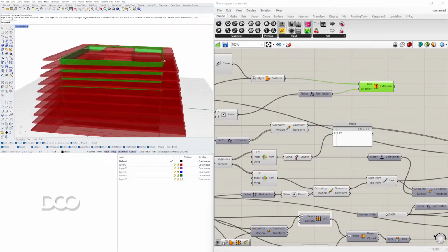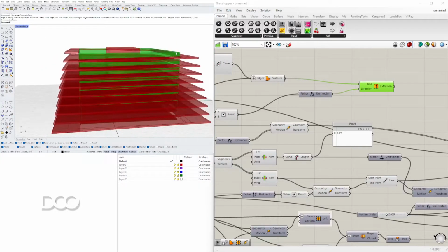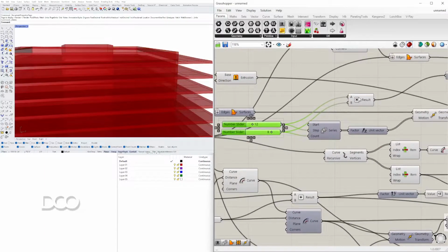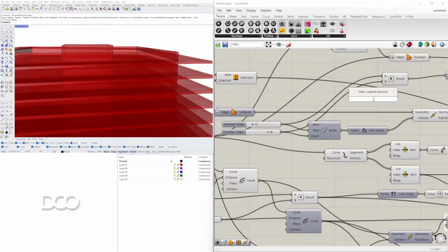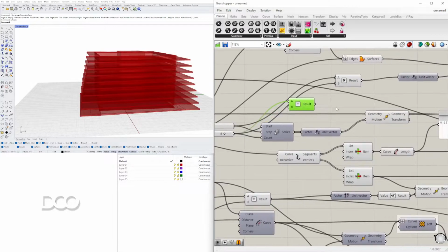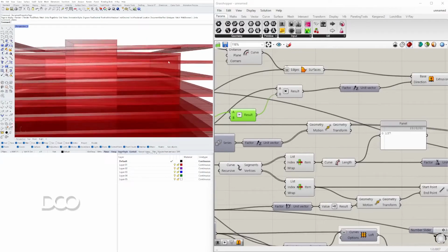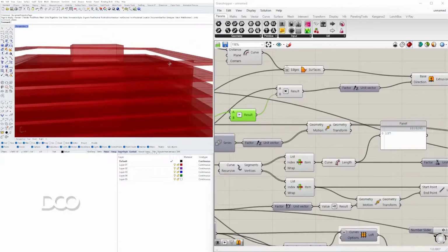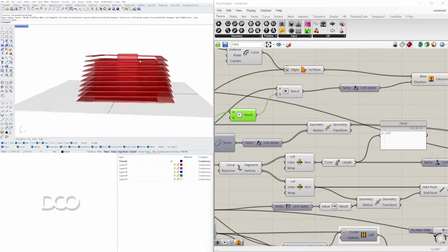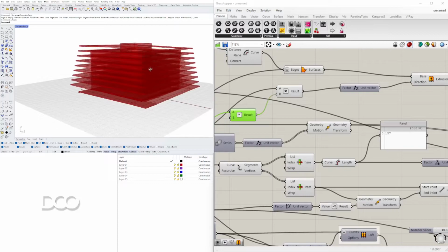And the walls will be going all the way up to the last floor. Now, if you didn't want it to go all the way up to the last floor, what you would do is, rather than 8, you'd do -1, which is actually what I want to do because I want to have a roof, open roof deck. So we'll do -1 and then plug that into B. And so now we've gone all the way up to this floor, but not all the way up to here because I want to have access to this area and for it to be more of like a lookout design.